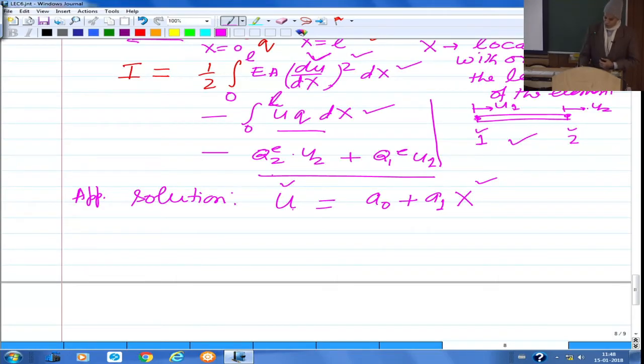Then we look at the continuity of the primary variables across the elements, and then look at whether we need more terms or fewer terms. In this case, whatever is required from the differentiability point of view also satisfies the requirement that primary variables are degrees of freedom at the nodes. So this polynomial is good enough.